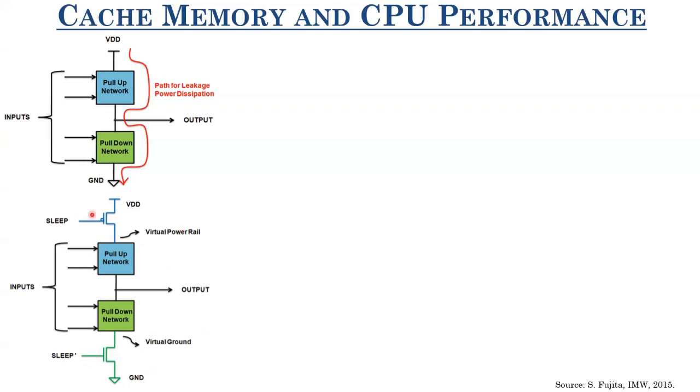So this power gating is an effective technique which is used in all the industries nowadays, in all the designs, along with clock gating, to reduce the leakage power dissipation. Now with this introduction to power gating, let me go to the fact that many times you leave your system or your devices, let's say your mobile phones or your processor or your workstations or laptops, in idle state.